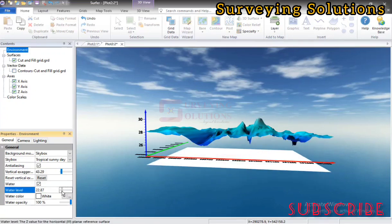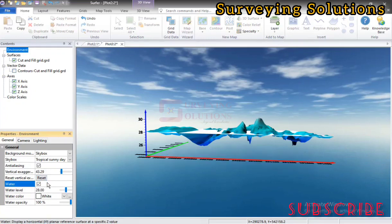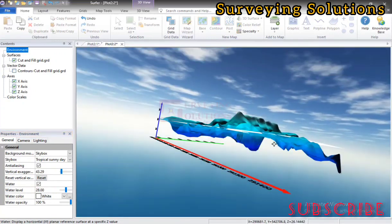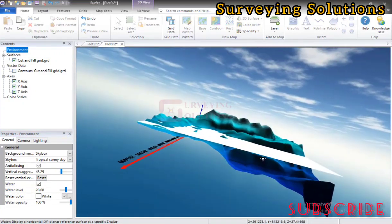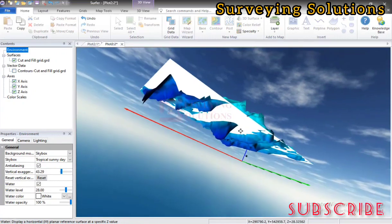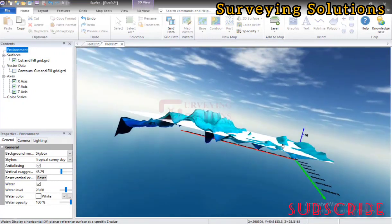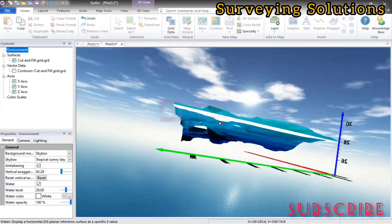Good. So for this particular video, I decided to use 28 as the water surface. So that 28 will give us a very good depiction of our second terrain, and it will help us to a great extent see the volume of cut and the volume of fill, right?